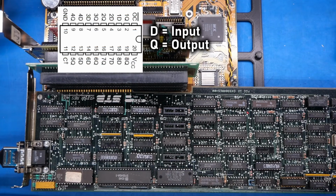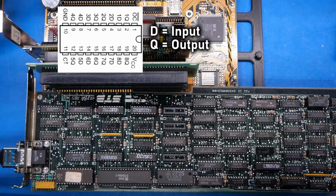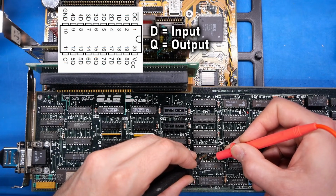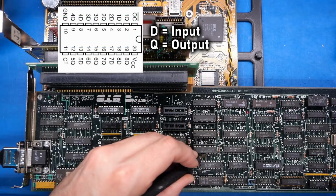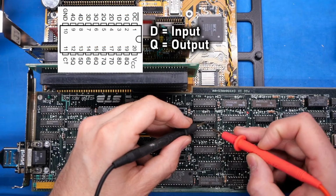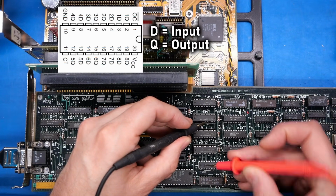Okay. So that pin there that I was just on is an input. So this chip is a suspect as well. And that means that this pin here is making its way there. That is pin 7, which is also an input. Okay, so that is the same suspect for these two chips. And how about this one? Where does it go? Does it go here too?